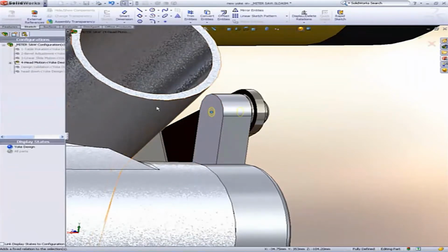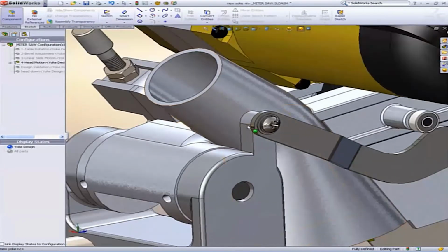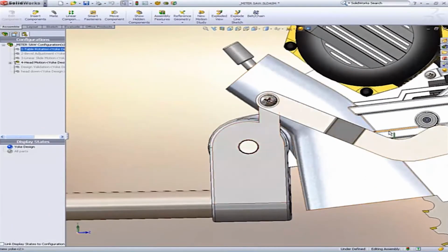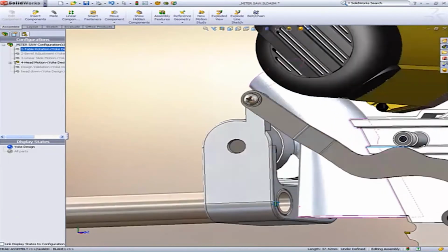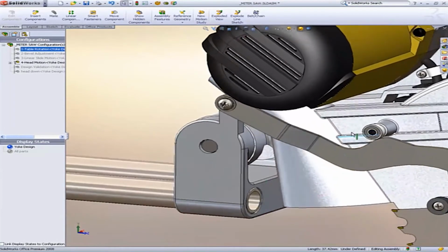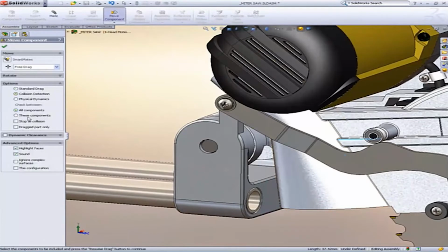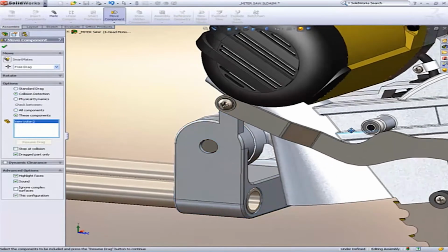Okay. You can see that the hole wizard does a great job for doing this. Now, here's a good time to test our assembly, how it actually functions. So let's move the assembly up and down, but notice that down there at the yoke, there seems to be an interference. So to check that, let's access the Move Component tool. Let's use the collision detection and select the yoke only.